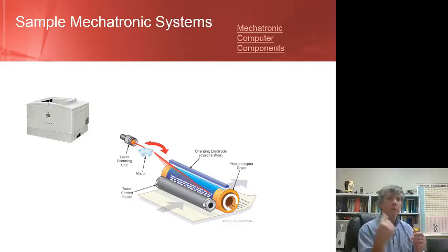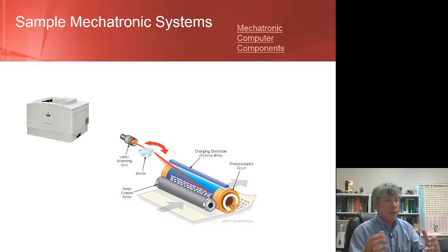Basically, the way it works is the mirror is constantly rotating, and the computer inside of the laser printer, yes, there's a computer inside the laser printer, controls it. It's trying to print an image, right? So it knows where we're at, what line we're on the page, and it knows what the pattern of light and dark should be. As the mirror rotates, it gives the printer the opportunity to scan the laser across the page, which then fuses the toner to the page to make the image.